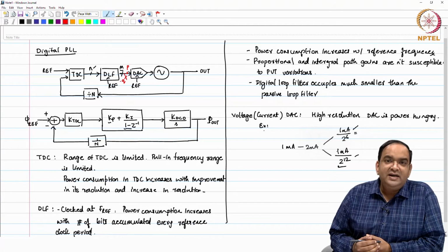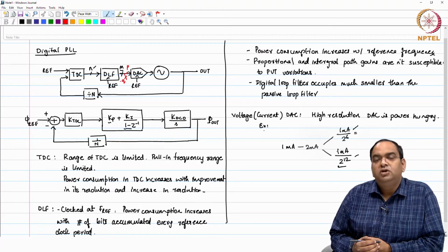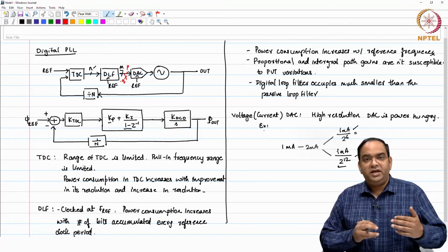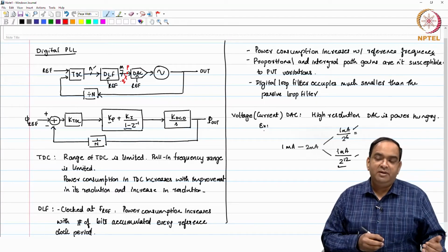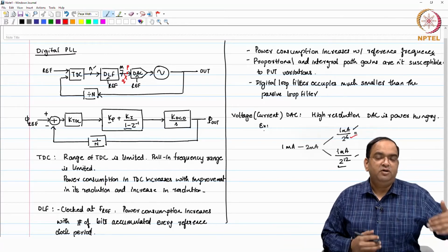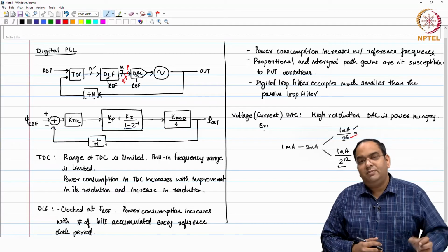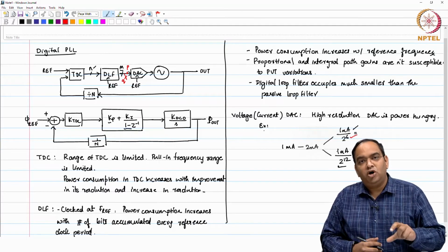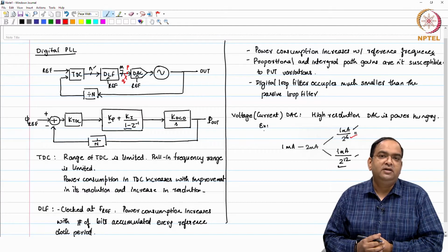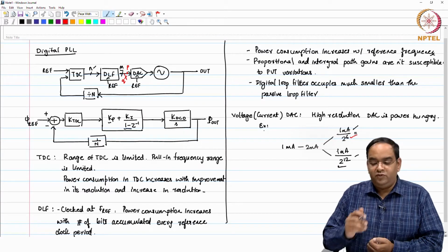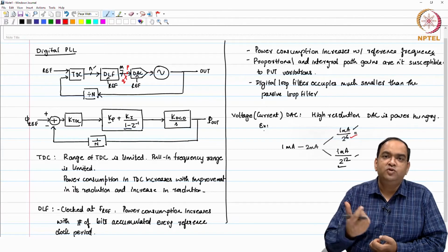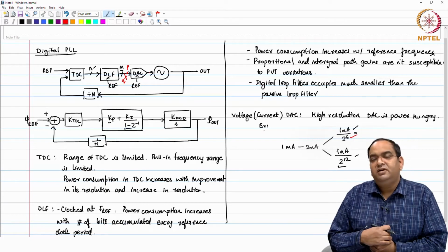So, there is a quantization which happens while the range will still remain the same. Earlier 12 bits span your 1 milliampere, now maybe 6 bits span 1 milliampere. When that happens, there is quantization involved, and this leads to quantization error in the DAC, which is going to change the frequency of your oscillator in a much coarser step, which is an error.